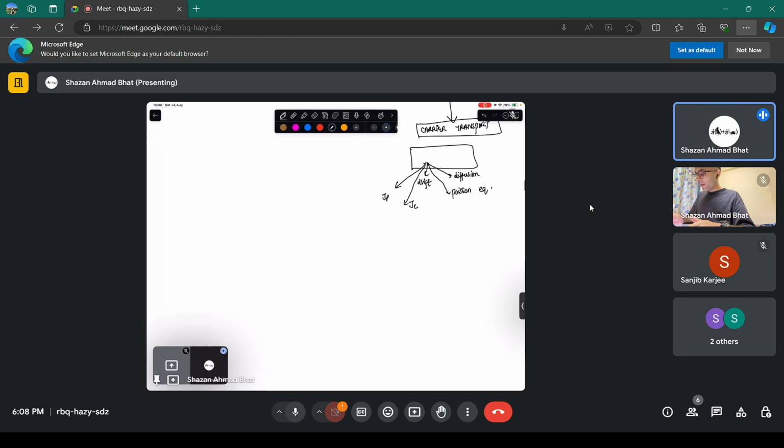And in order to fully capture the carrier dynamics inside the device, you need to solve the drift, diffusion, Poisson equation, something called self-consistently. What we mean by self-consistent is that you need to solve those equations in a consistent fashion.